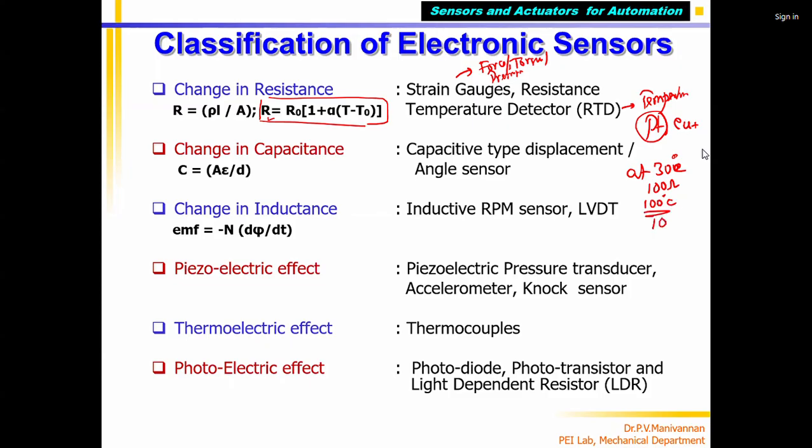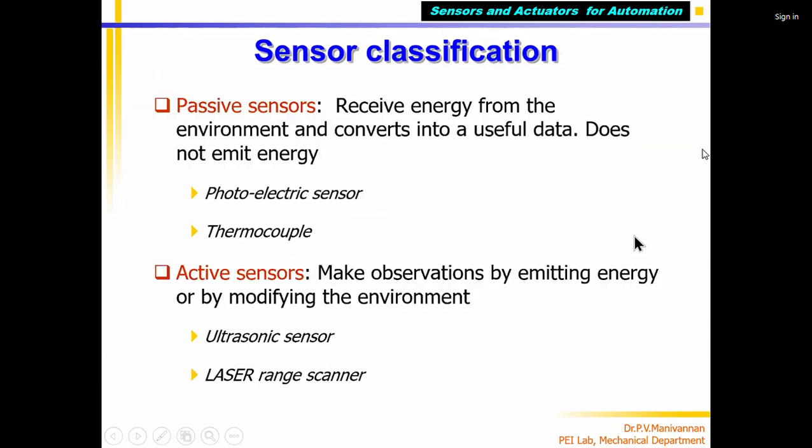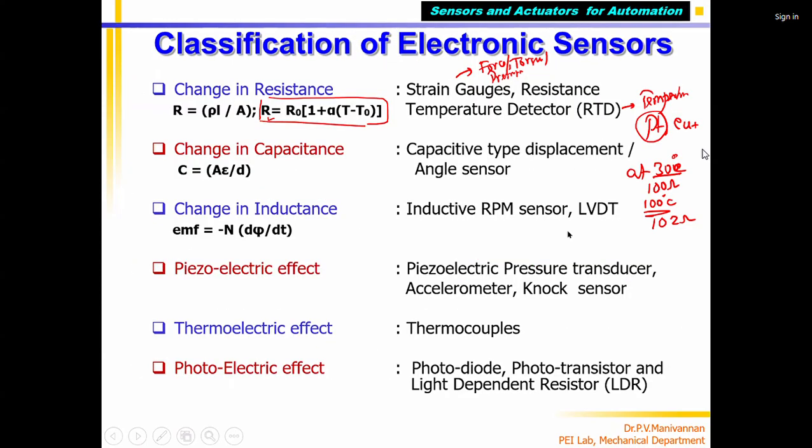Now the resistance may become 1 or 2 ohms. The platinum wire, which is called an RTD, resistance temperature detector, is subjected to higher temperature, lower temperature. Automatically, the resistance changes. So this property is used for measuring temperature. How the temperature and resistance are connected is this formula.